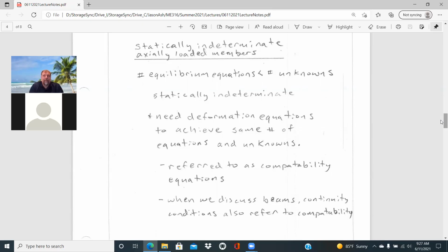And in those instances, as you look along the length of the beam, you can't have at one point displacement, say of 5 millimeters, on the left-hand side of the point, and 10 millimeters on the right-hand side of the point. They both have to be the same value at that given point. And so you need a nice flow of that displacement curve to maintain continuity within the length of that beam. The same is true for the slope. The slope is going to vary with respect to that x position, but you can't have an abrupt change in slope.